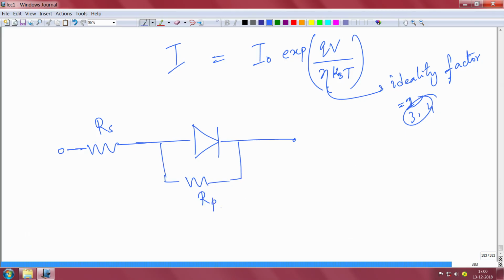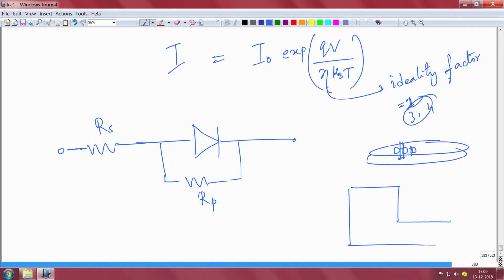It basically is the dislocation or any other parallel leakage path, surface leakage. Suppose this is your LED wafer on which you are making many LEDs, but the current will be flowing top down. As I told you, this is your P GaN, for example, this is your quantum well, and this is your N type GaN.